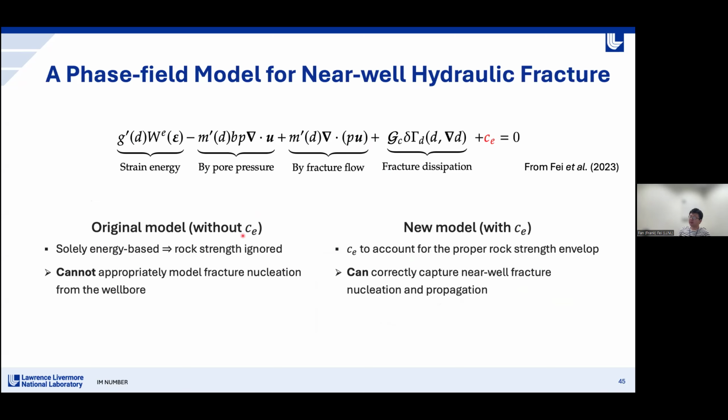The problem is that the original phase field model, the most popular one used in hydraulic fracturing simulation, is derived in a solely energy-based way. But for near-well hydraulic fracture modeling, it's important to accurately capture the nucleation of the fracture, which is actually determined by the rock strength.